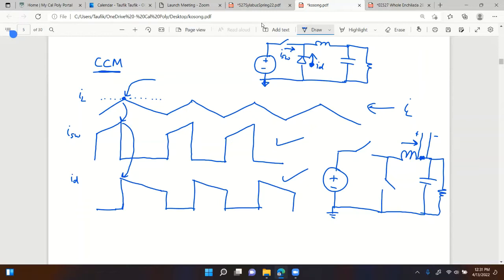That's why you use a sensing resistor. But if the resistor is over here, then you only need one voltage because the other voltage is ground, 0. So it's a simpler circuit to implement the sensing. That's the number one advantage. What is the other advantage?